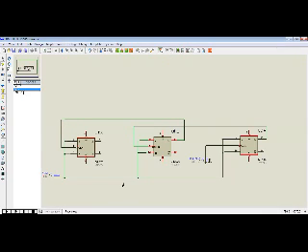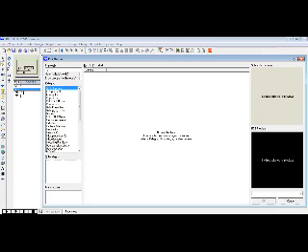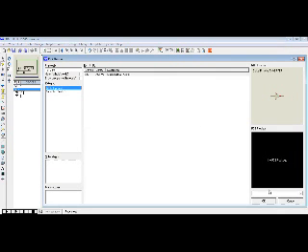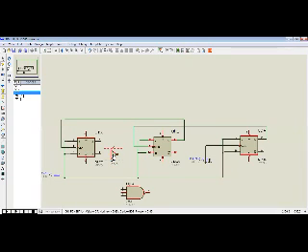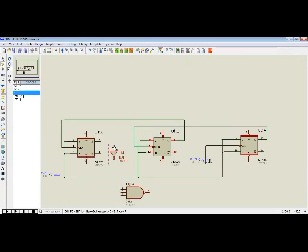So you can connect it here. Then to it, I need a NOT gate so that I can invert the second output. We need a NOT gate, which we can rotate, tap the output of the second flip-flop, which is that output, and connect it as the second input to our NAND gate.